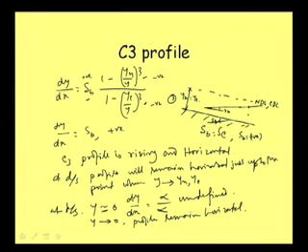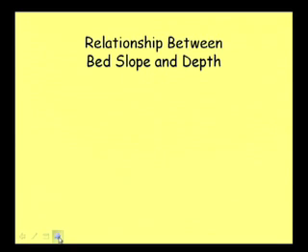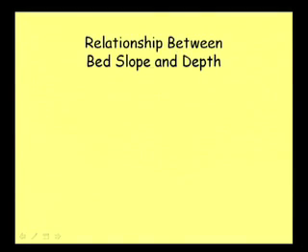Now, if we go by this expression, then we can see that if we put SB equal to 0, then whatever value this part comes to, it does not matter, dy/dx becomes always 0. But that is not the situation. So the simplification we have made here will not provide us an exact answer for the horizontal slope situation, and that is why we can have a different approach for analyzing the flow profile.